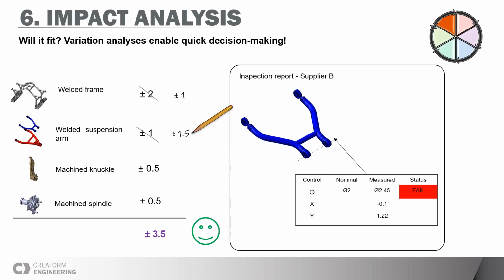And in that case, we can see that one dimension that is out of tolerance is not necessarily a direct indication that we will fail a functional requirement. It's just an indication that we need to take a look into it. Unless all dimensions that we see here were out of tolerance and also in the wrong direction, we should be able to meet the final requirements. This is also a reason why we might want to include some statistics in our analysis, but that would be a subject for an entire other webinar.